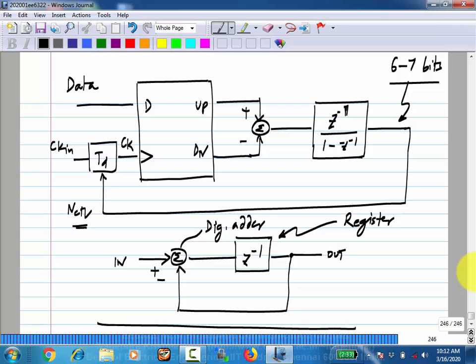So this is how it is. Conceptually, this is what it is. And essentially, when you have a single accumulator and something like this is up and down, the whole thing is equivalent to an up-down counter, right? You have up here and down there, and that's all. Okay, this is fine. Any questions about this? So this is actually a favored way of doing things these days. I'll go to the clock and data recovery circuit without forwarded clock, and it becomes clearer why that's so.